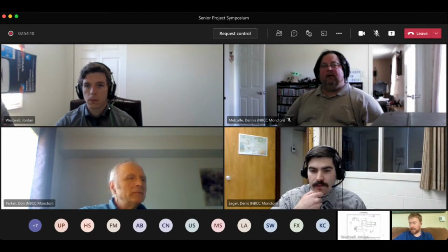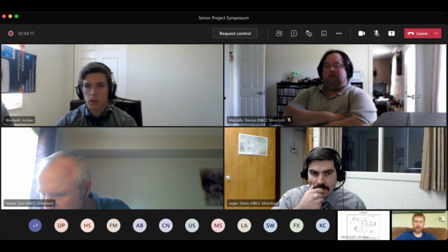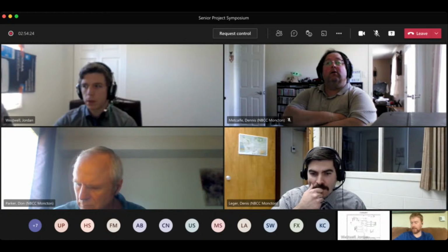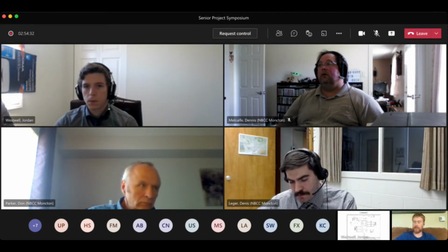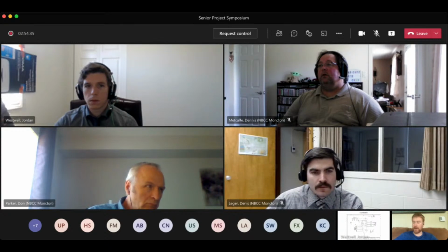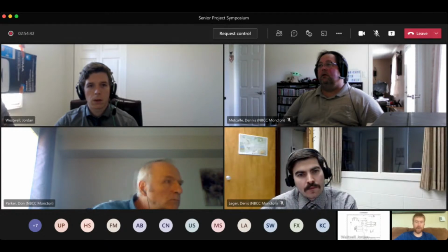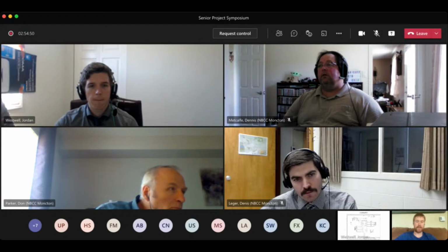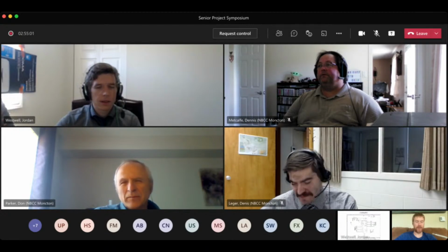You referred to C3 and C1 as decoupling capacitors. Are those decoupling capacitors? As far as I'm aware, they are voltage smoothing, so yes. Well, from earlier presentations, we noted that decoupling capacitors are normally located near the power supply input pin on an IC, such as your 328. So C2, I would definitely say is a decoupling capacitor. But would you call C3 and C1 decoupling capacitors? I mean, I guess not, but. Okay, so if not, what is the correct term for them?